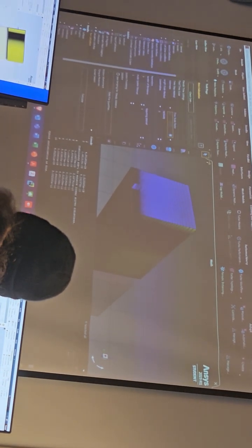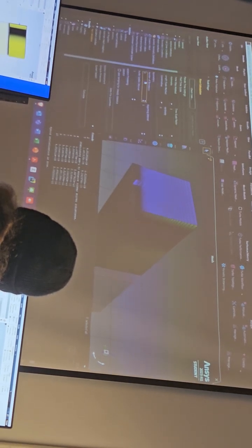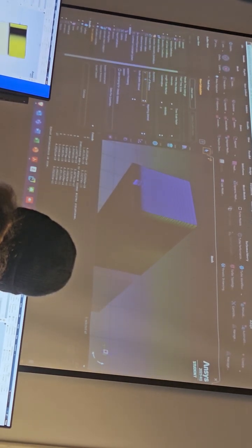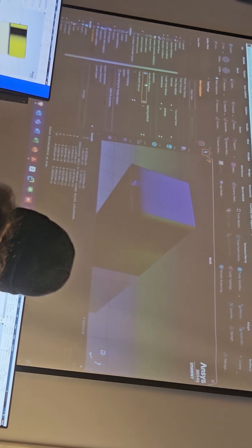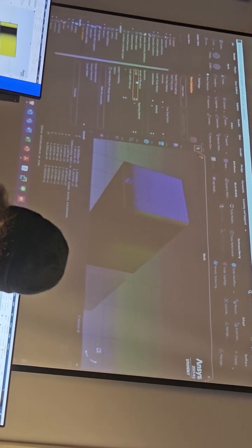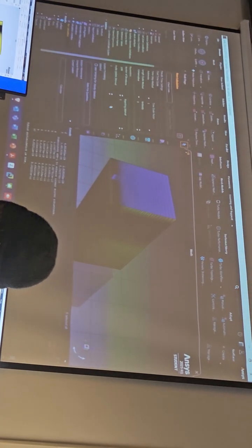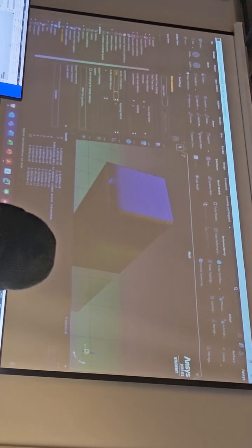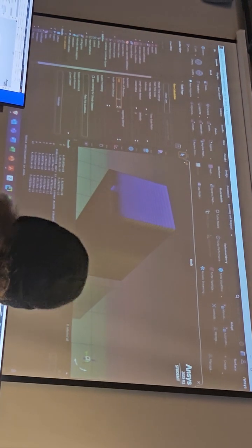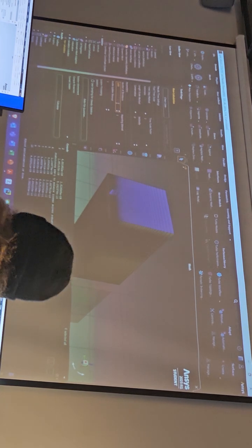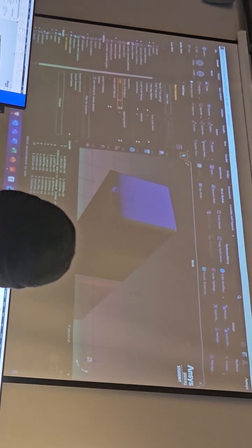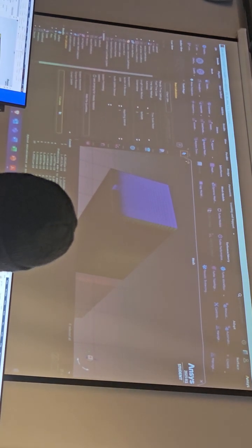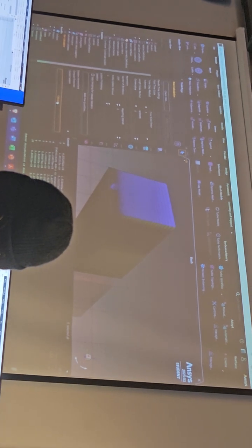And then we can leave it at 1 for this case. And for number of iterations, I set it to 1000. We'll need less than 1000. So when our residuals, which we set to 10 to the power -5, are met, then the solver is stopping. So we can calculate after that.